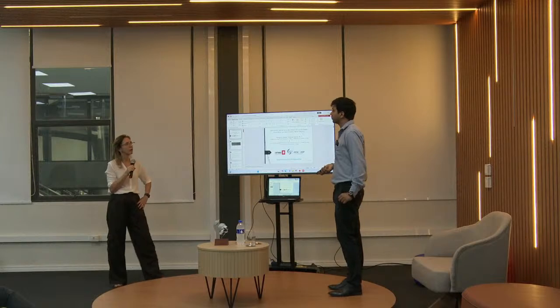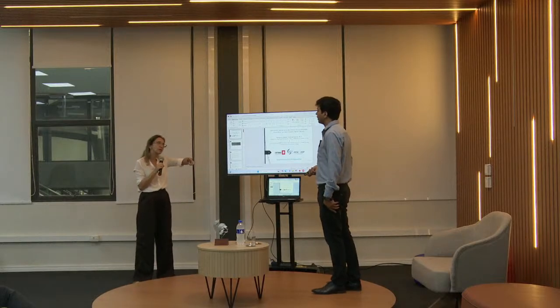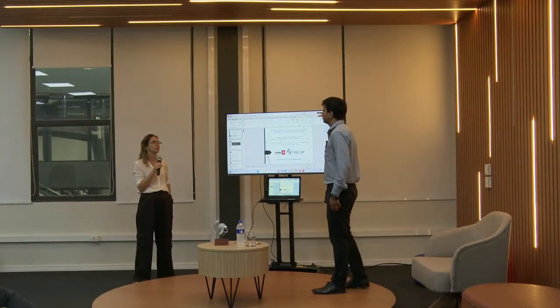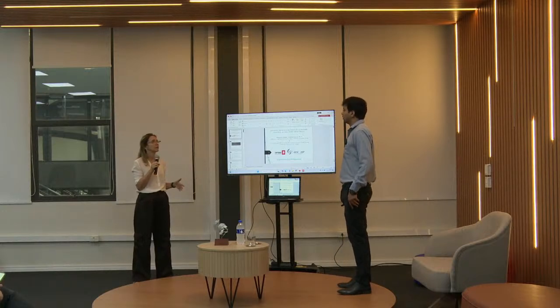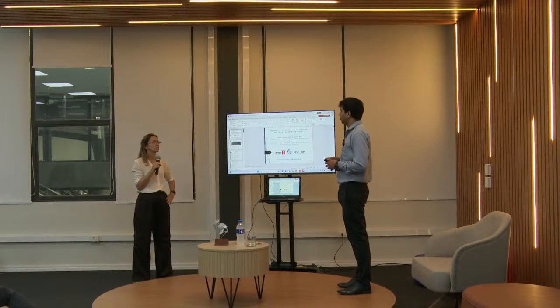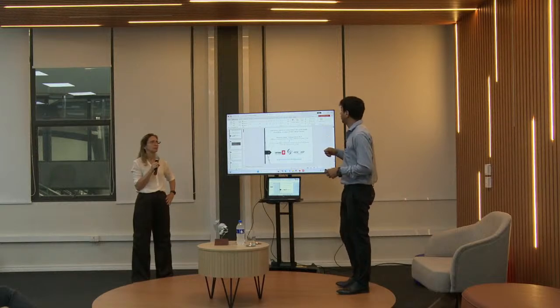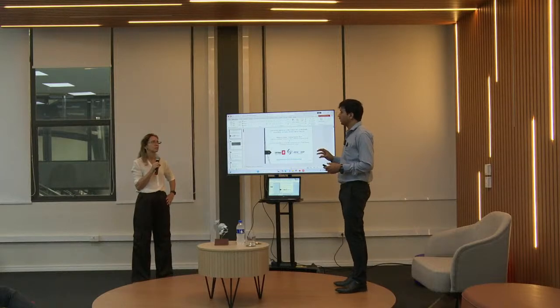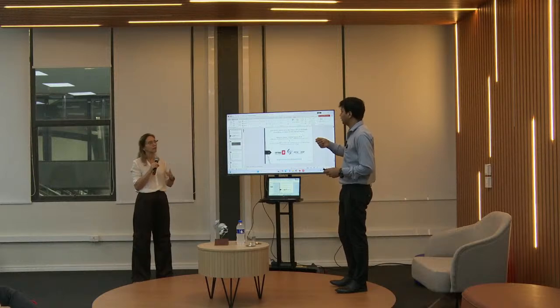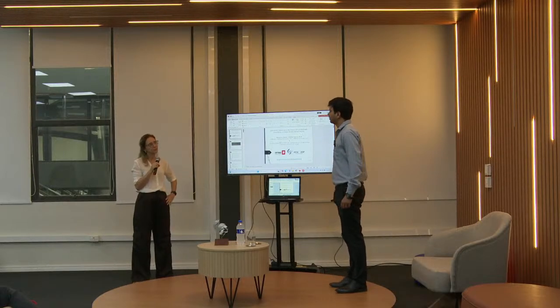There's more equipment you use there to install the nail? The helical nail needs small equipment. For conventional soil nail, I think we require more equipment, because we require a drilling machine, pressure grouting, and the nail. But for the helical soil nail, we only require an installing machine. Okay. Yes. Thank you. Thank you.